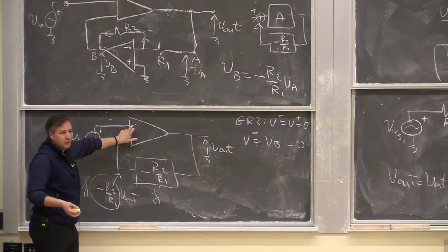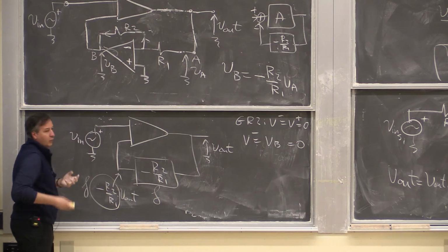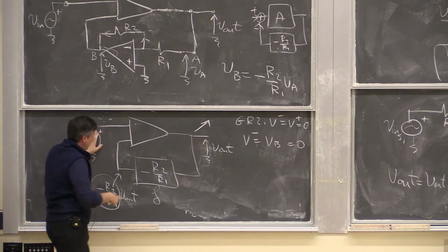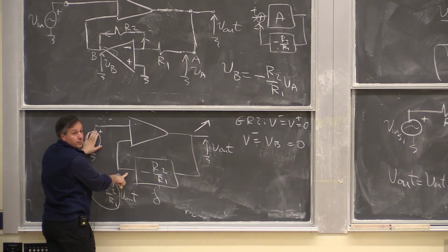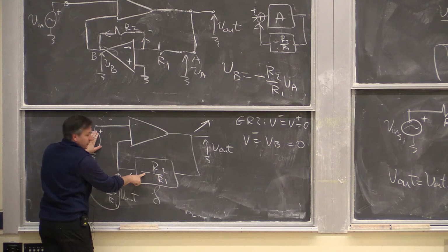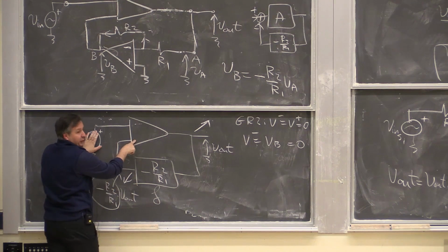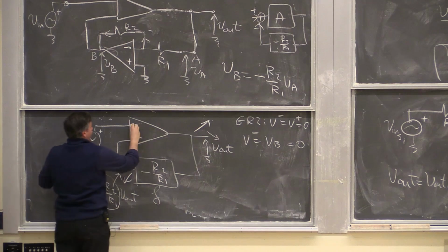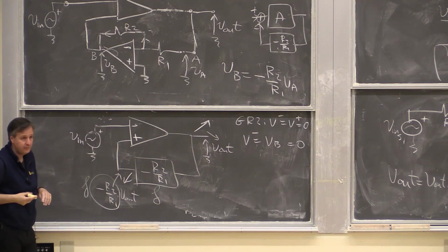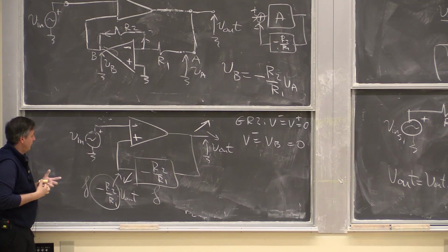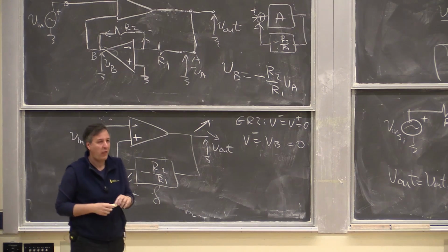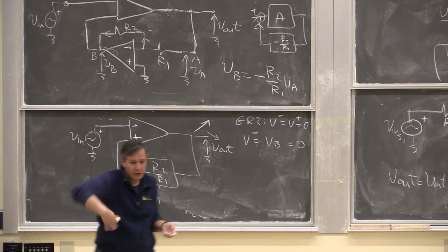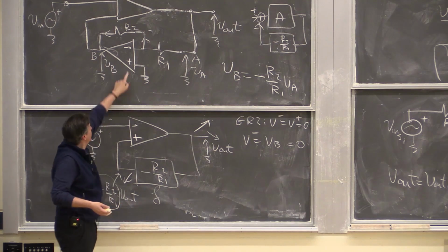So let's take a look at what the polarity should be here. We do that by following the loop. We null the source. If this increases, what happens with this voltage over here? It decreases, because of this sign inversion. So if this decreases, what does the polarity have to be here so that this decreases? It has to be plus, and then this is a minus. Does this make sense? We have inverted the polarity in the feedback loop. Therefore, it's logical we now have to feed the plus port. Previously, if we were not inverting polarity in the feedback loop, we would feed the negative port, just like here.